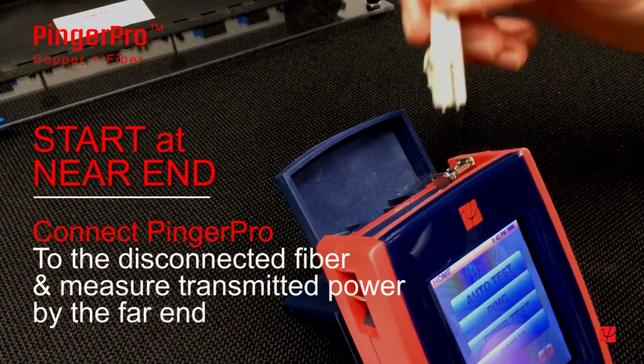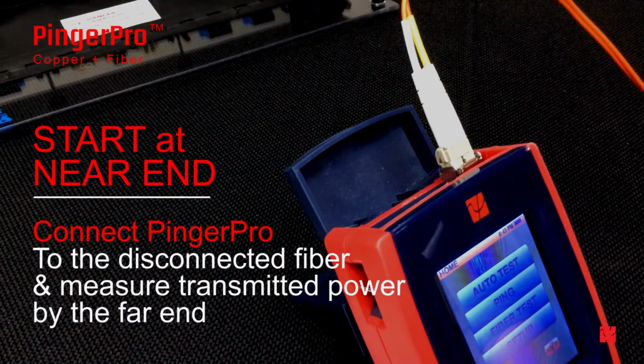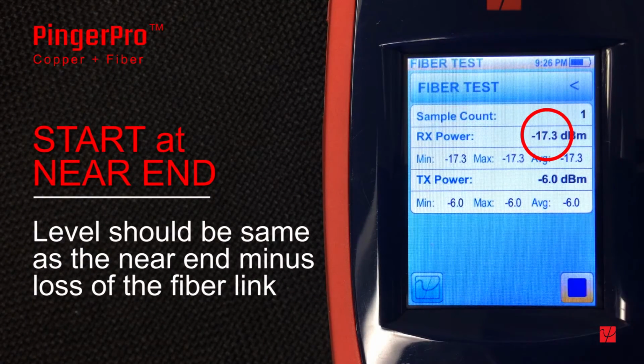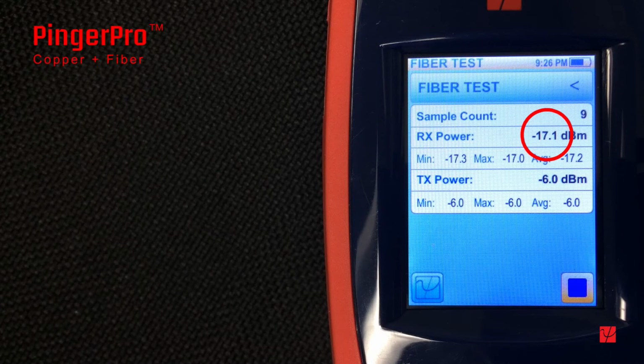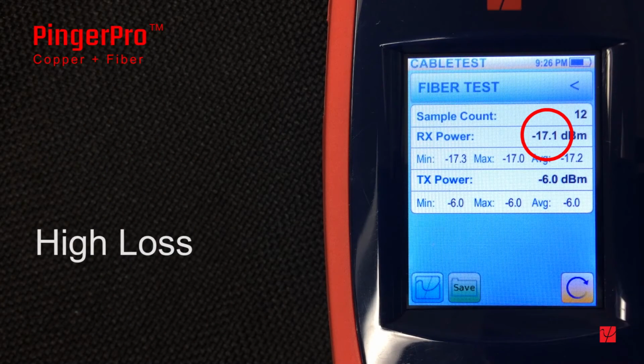Next, connect the PingerPro to the disconnected fiber and measure the optical power transmitted by the far end. The level should be about the same as the near end minus the loss of the fiber link. Fiber link loss should be relatively small unless it is a very long link or has many connections. In our case, there is about 11.1 dB loss, which is excessive and indicates that there is a problem between this point and the far end.